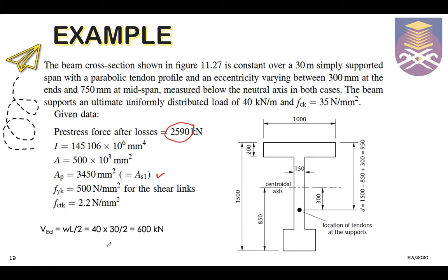The VEd value here is calculated based on this uniformly distributed load of 40 kN/m. How we calculate the VEd value is a simple calculation, using the wL²/2 equation. So we have here 600 kN as our subjected shear force.